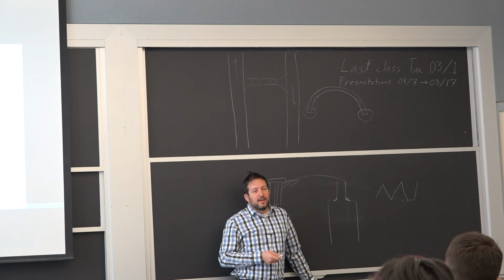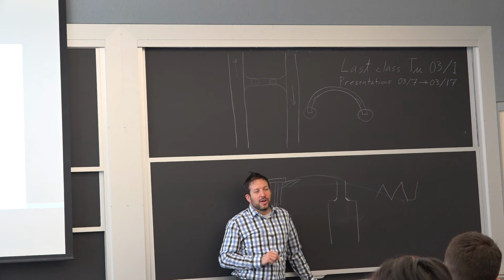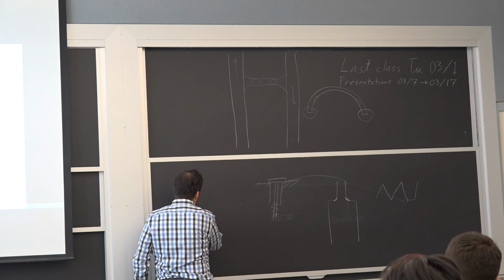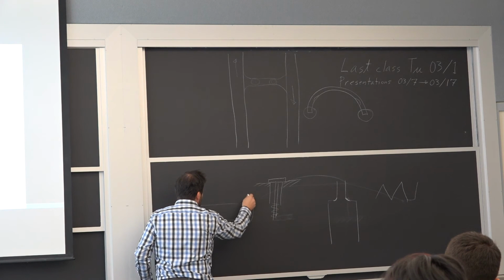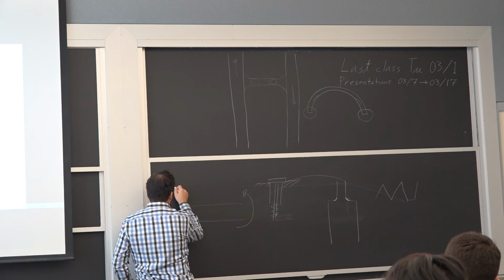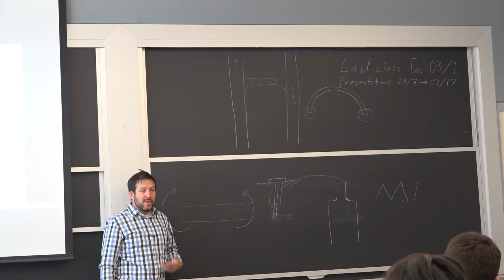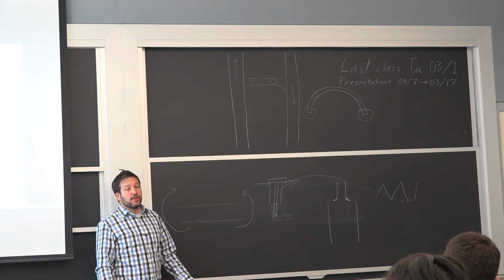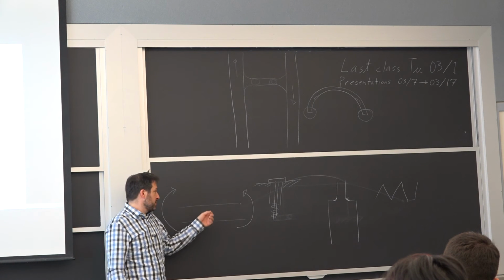But it's not by specifying just the overall roughness of the part in general that you'll gain a lot. If it's a great shaft that sees no wear, that is one example. Let's say this is loaded in bending, and there's no discontinuity. This is a very smooth surface. Yes, you may be able to raise it maybe 20, 30% by having a very nice finish here. But a lot of times there will be something else.